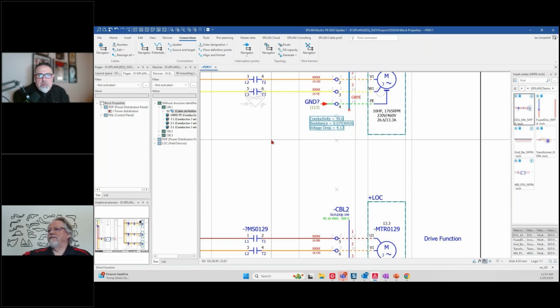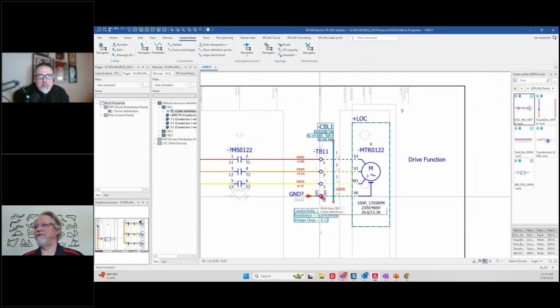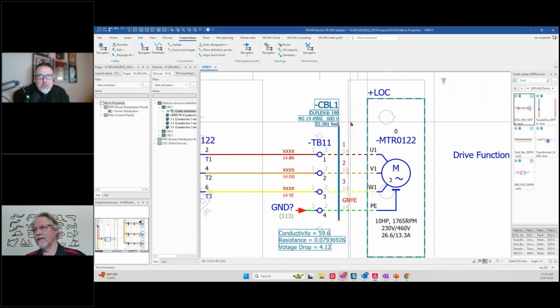Also, one of the things that makes the calculation of the volt drop a little more difficult is that here in the States, we don't use SI units. All the calculations you probably read are based on SI units. The one that I read for the volt drop was based on conductivity, which is in Siemens, and the cross-sectional area of the cable in square meters, not AWG.